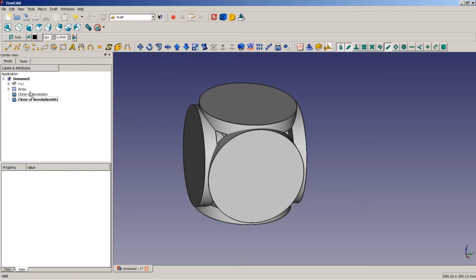and this is one of the limits of FreeCAD at the moment. It is of importance at which point in the history of a part you did the clone. If I change the sketch or the revolution at some point, the clone will also change. But if I add something to a revolution, the clone will not change, because the clone was made at a point in the history of a part when only the revolution existed with the sketch.